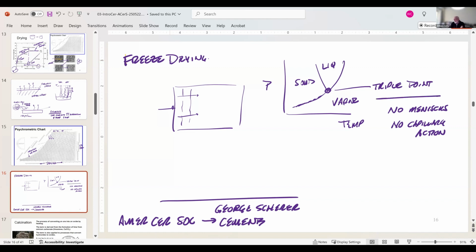It's a different aspect than evaporating water from the surface because you're actually subliming the solid in the system. I don't know if that's helpful to your answer. Does freeze drying have similar characteristics? It is different because you avoid the capillarity in the system, so you have less chance of damage, is my recollection. But there's a potential for segregation.